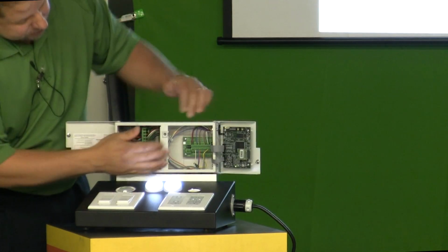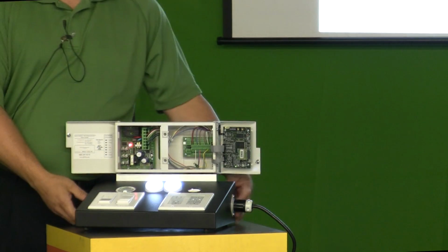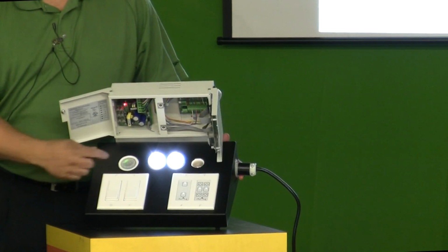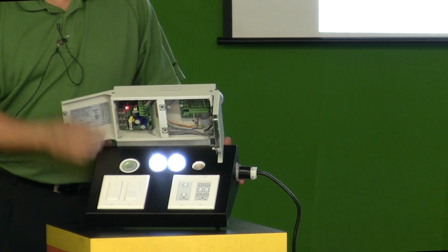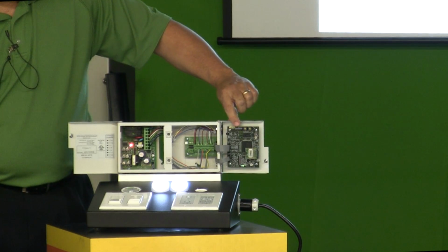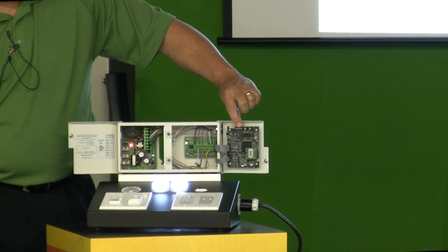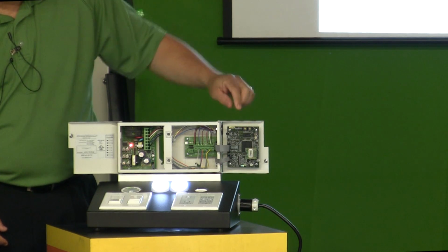This is the low voltage section, so you can see here I've got 6 universal inputs. I'm actually powering up this aux sensor out of that UI, so that's 24 volts DC going to that occupancy sensor. No power pack, nothing else, right? Here's the controller board. You set your BACnet baud rate here on the DIP switch. Your MAC address is set there.